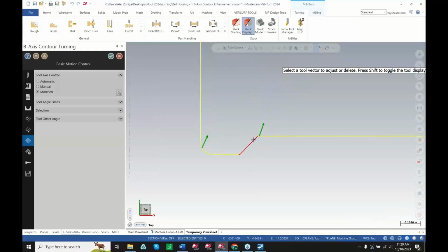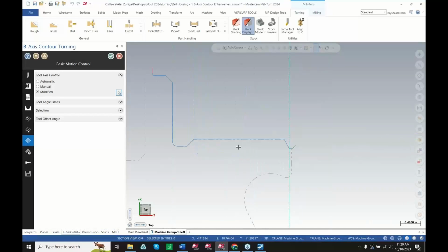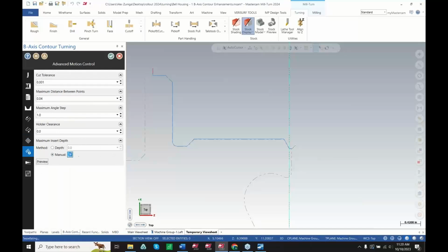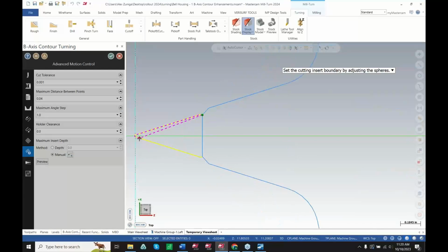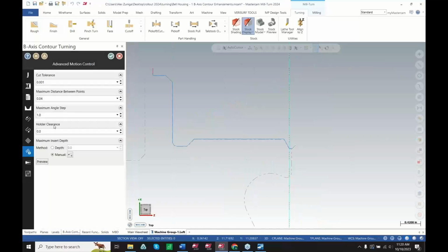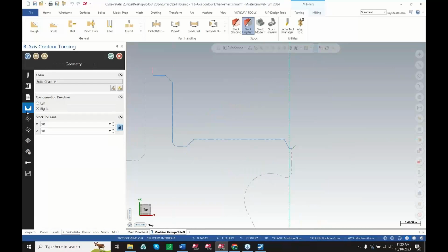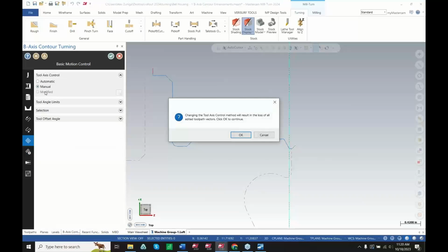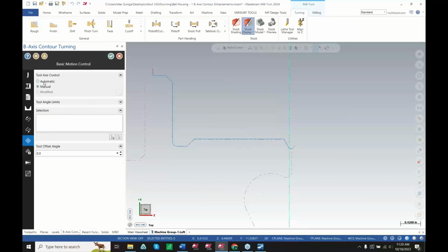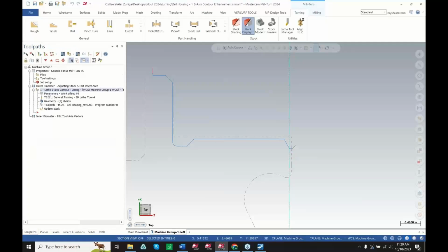You're seeing this red here because the tool knows the back of the insert is being touched with it. So we can go and readjust that section over here and say, hey, maybe we have a little bit more room to breathe with that insert there. Oops. Cancel that.